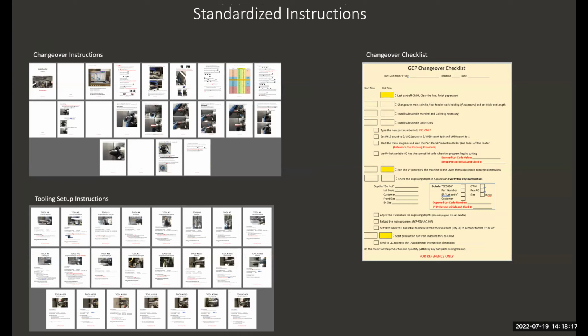Changeover instructions were created to document the physical work holding changes needed from one part size to another, and were done in a step-by-step fashion with pictures. Tooling setup instructions were created documenting how the tools are set up in the machine. Notes related to tool changing, what features they are cutting, their safety monitor load settings, expected tool life, as well as what dimension is directly affected by changing the tool.